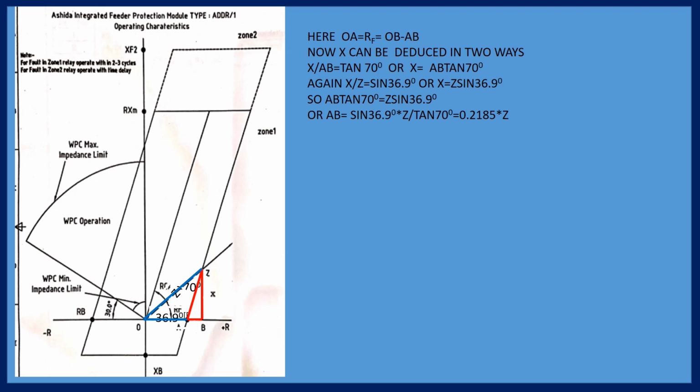It is the same on the 132 kV side and on the 25 kV side. That is also the same theory. At one end the current is going to the OHE and returning it is going to the transformer. So the direction is reversed in both cases. Again here, on the 25 kV side also, we are connecting S1 to S1. I think it is clear to you.